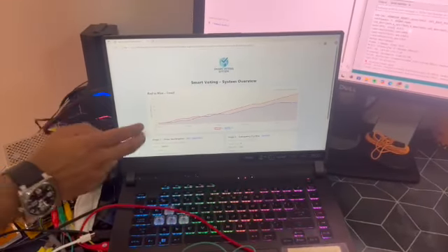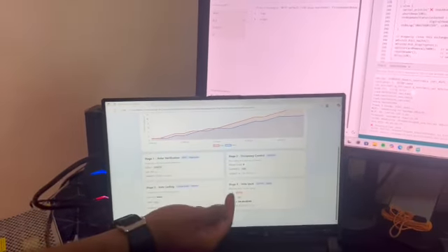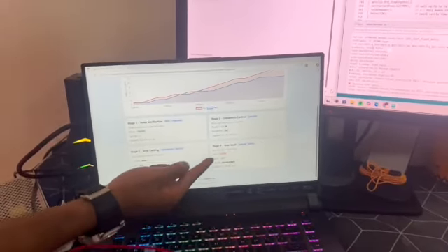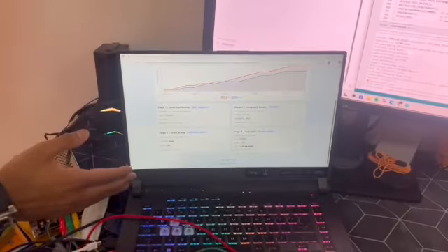For example, in stage 1, it shows the status, whether the user is verified, the update and the UID of that person's card. Stage 2 shows the occupancy control room, the people count, availability, and its last update. Stage 3 shows the vote casting system, where it shows the last vote, the state, and also the last time it's updated. And finally, stage 4, the vote vault, which shows whether the system is locked, the buzzer is on and off, and the last UID of the card used. This system refreshes every 10 seconds.